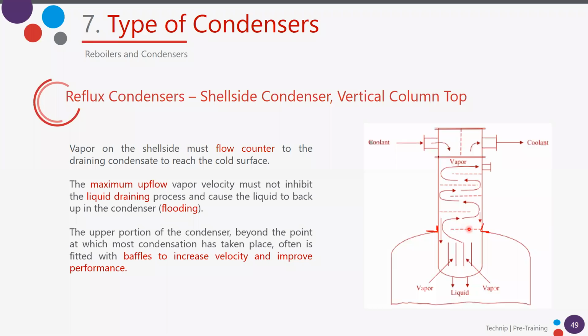Otherwise, imagine there are no baffles, the fluid would just go up with nothing forcing it to move, so the velocity is lower. With the baffles, we redirect our fluid and force the velocity up. Increasing the velocity means increasing the heat transfer coefficient.